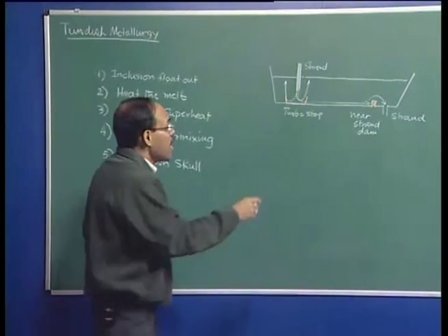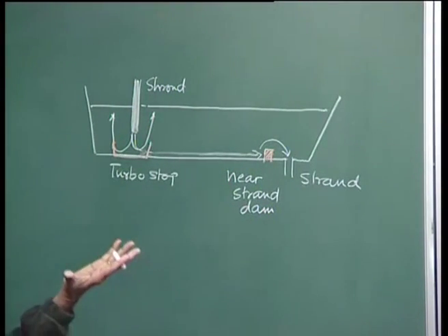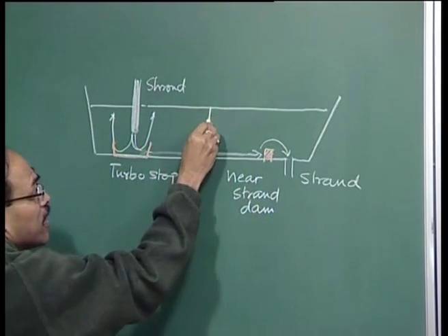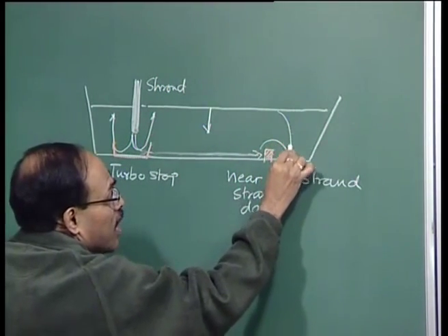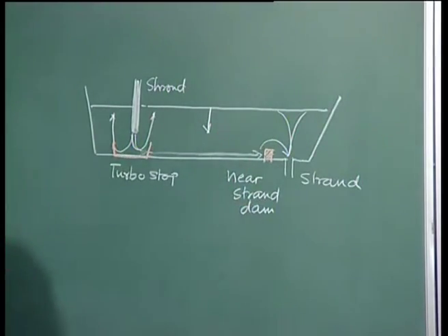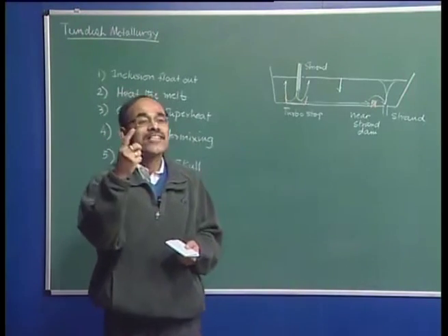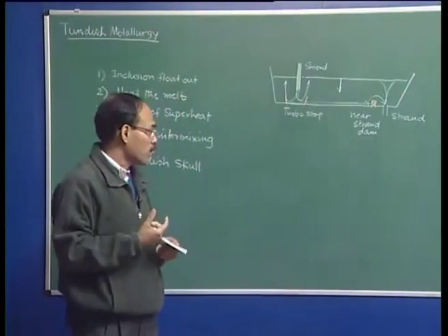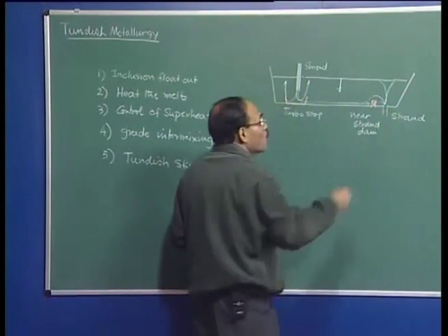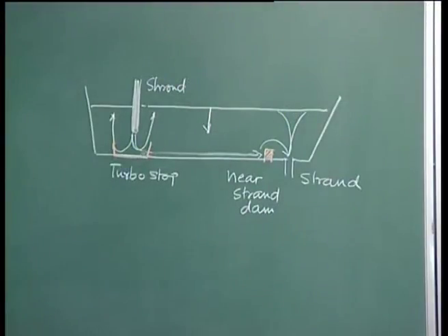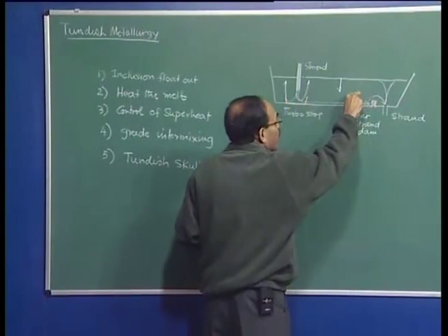So, imagine the last heat and you have metal in the tundish, and nothing is coming into the ladle, because that has to be the last heat, and then this interface goes down, and at some point slag vortexing is going to start, just like when you open a tap in a sink, you must have seen that funnel vortex form. This is the characteristic of draining vessels, also in ladles and tundish through the strand or through the well in the ladle. We have vortex formation or slag entrainment when the level of the metal falls to a threshold level,